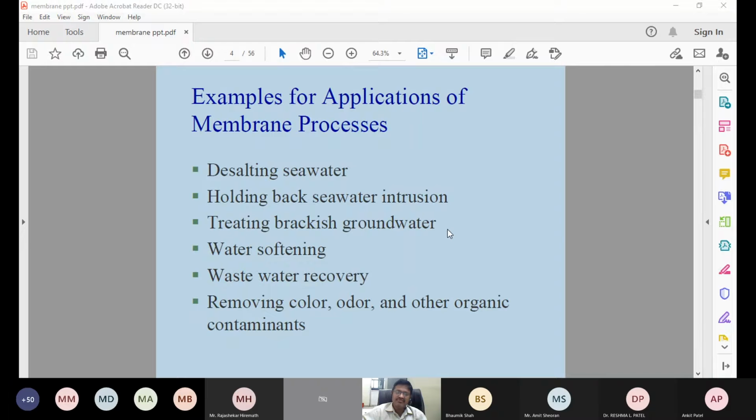We should know what the source is. If it is a groundwater source, sometimes your dissolved solids are more than 500. Then you can go for an RO membrane type system. Otherwise, you can have ultrafiltration or microfiltration, followed by something like AquaGuard UV. They have only ultrafiltration, microfiltration, and then a bacterial removal technology, that is UV light.